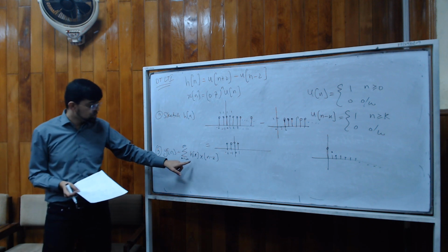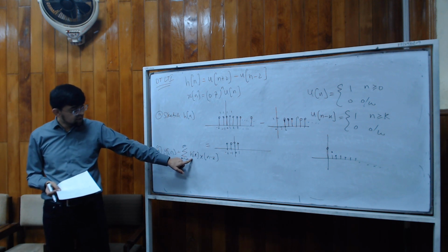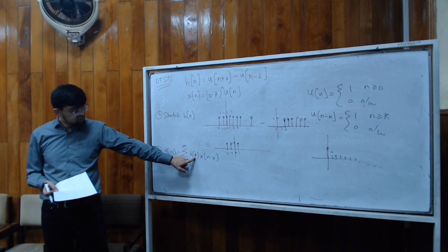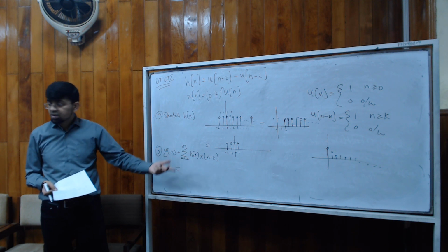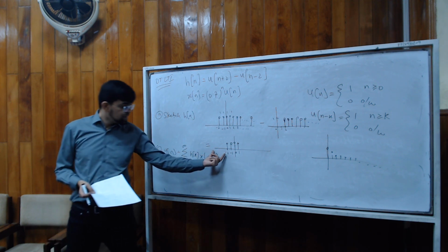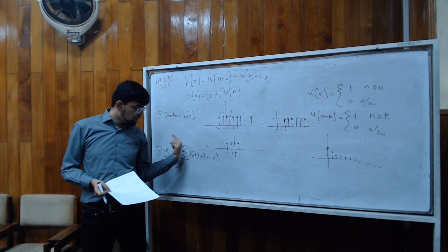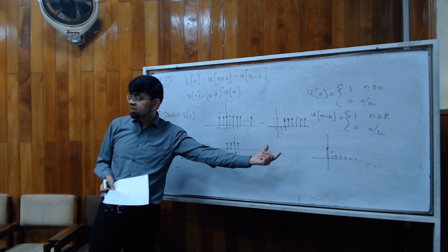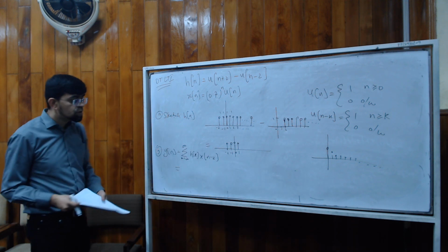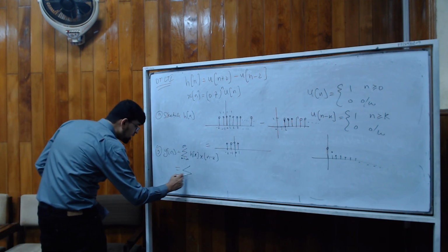If you're smart and look at it very carefully, you will see that for what values of k is h[k] non-zero? See, h is 0 for all the values from -3 onwards, and here from 2 onwards, h is 0. So you don't need those terms. So k can be limited.